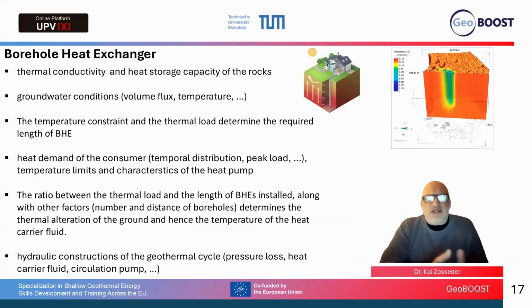Of course, what is important for borehole heat exchangers are the underground parameters, like the temperature of the underground, the thermal conductivity of the underground, and the heat storage capacity of the rocks. These are key parameters which should be assessed in the planning phase of such a borehole heat exchanger. You can measure them with specific measurement devices, and this should be done beforehand.